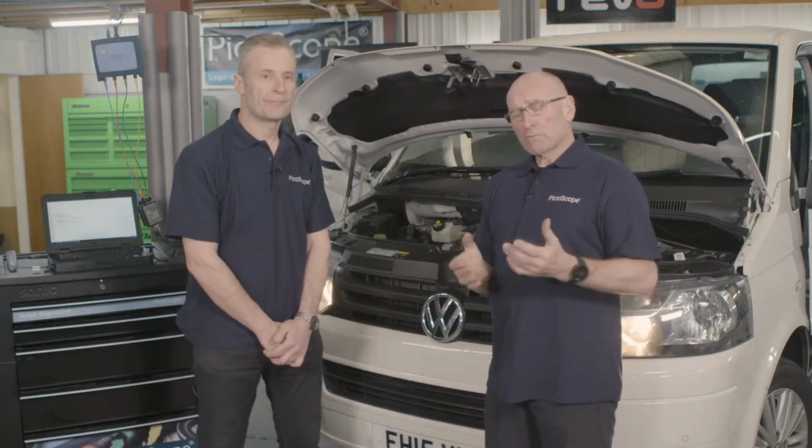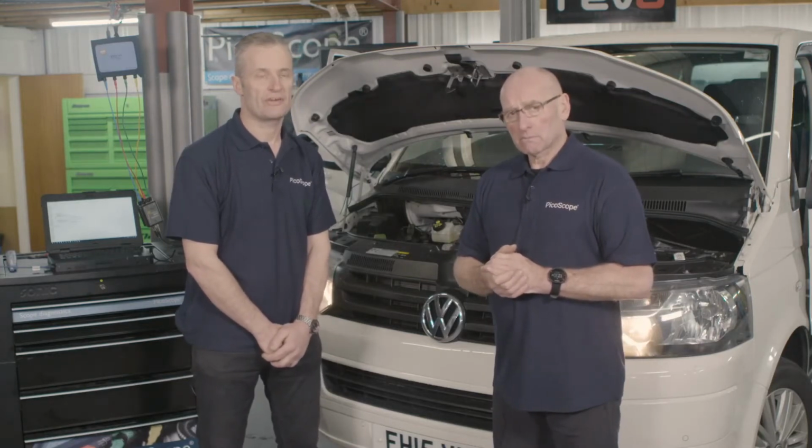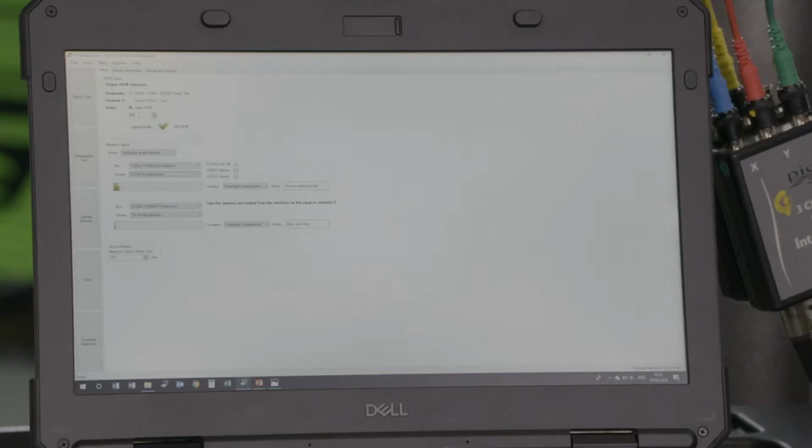Would you also recommend multiple microphones in the same way you would accelerometers? I would, most certainly, yeah. The advantage of the accelerometers is we lose a lot of the ambient noise. However, the microphone gives a real, true representation of what the customer can hear. So always include a microphone in these kind of measurements as your customer reference, an indication of what the customer can hear.